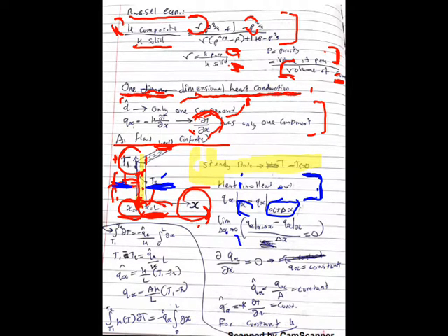Now, let's jump over here. This is basically reiterating the same thing, no accumulation term, meaning there is no change in Q across x. Like we said, steady state, that is all it means, and it is redefined over here as the limit. Now, all of this stuff over here, let me put some green in there. All of this stuff over here is saying literally the exact same thing. Steady state means no heat accumulated. Heat does not change across x.